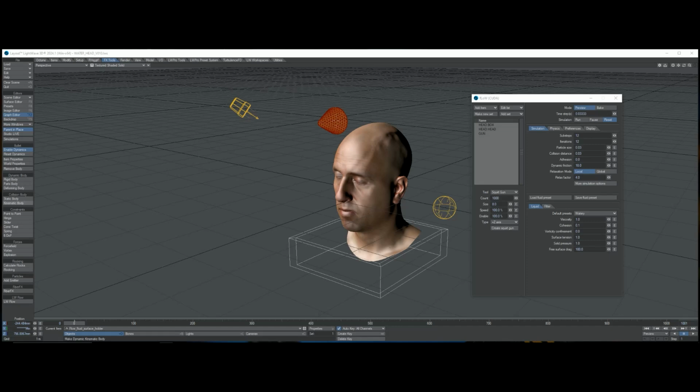This scene will show you how you can build fluids with Flow CUDA if you want the fluid to stick on an object. Normally, if you build a setup with Flow CUDA with the default settings and run it, this would happen: the fluid comes in contact with a kinematic object, which is a collision object, but the fluid would purl up from that, or purl down from that object. You have that gum-like, thick fluid. It's not water, it's more of a thick fluid. But you see that the fluid does not stick on that kinematic collision object.